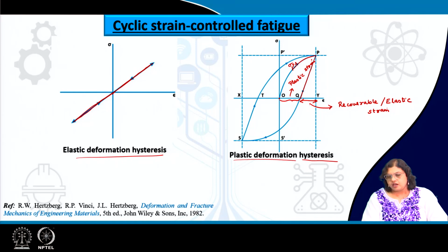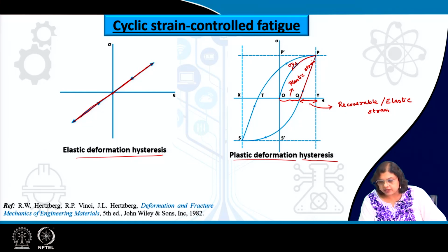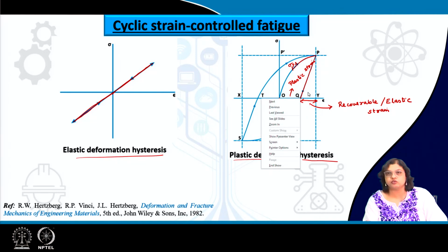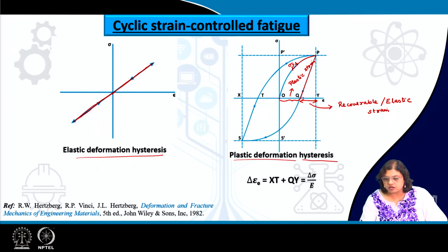Okay. And if we are coming back to the zero loading scenario at the point of Q, and we try to impose the compressive load, then from Q to S prime, it is still having some amount of deformation, including both the elastic and the plastic part, and then it is moving forward up to the point S. So, the yielding is happening here, and then it is moving up to the point S where there is only permanent deformation.